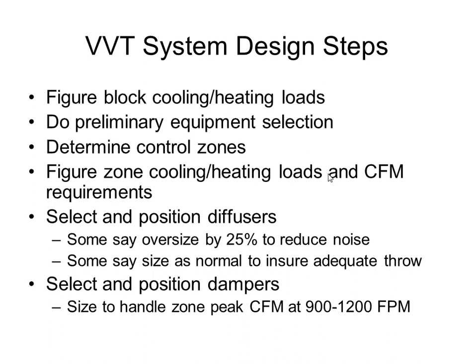Once you have your general idea of what large equipment you're going to get, then we move into what zones we want to do in the system, where we want to have the control dampers. So we get to decide where our zones are. Now we need to calculate our loads and CFMs for each zone. Again, doesn't always happen. If you have an existing system, you'll see a damper size. You'll say, hey, use that, but we always want to design it if possible.